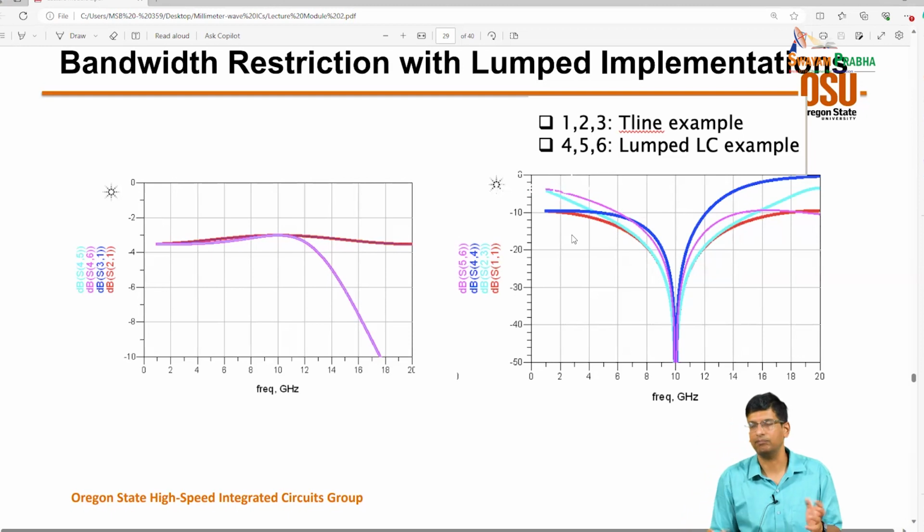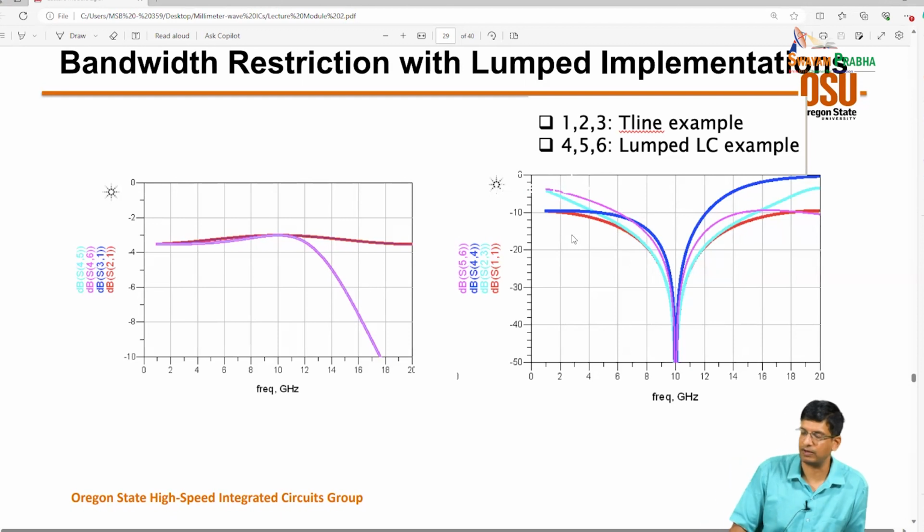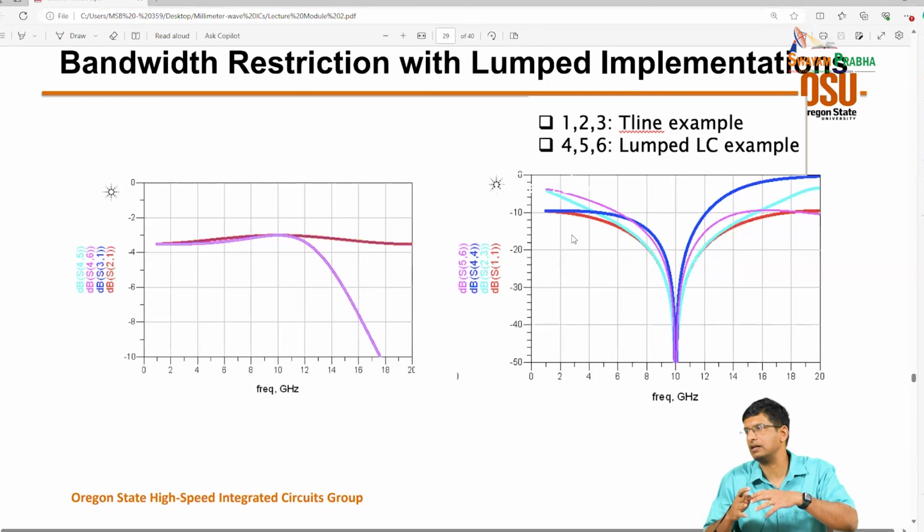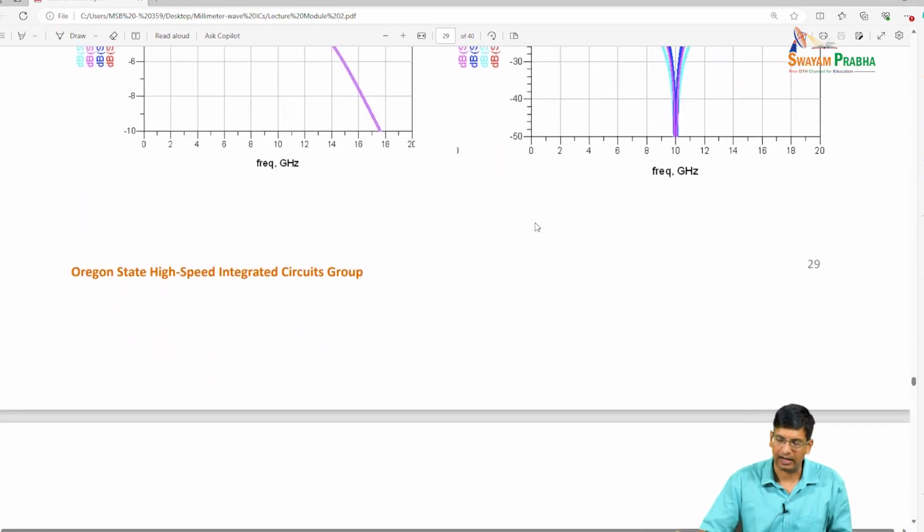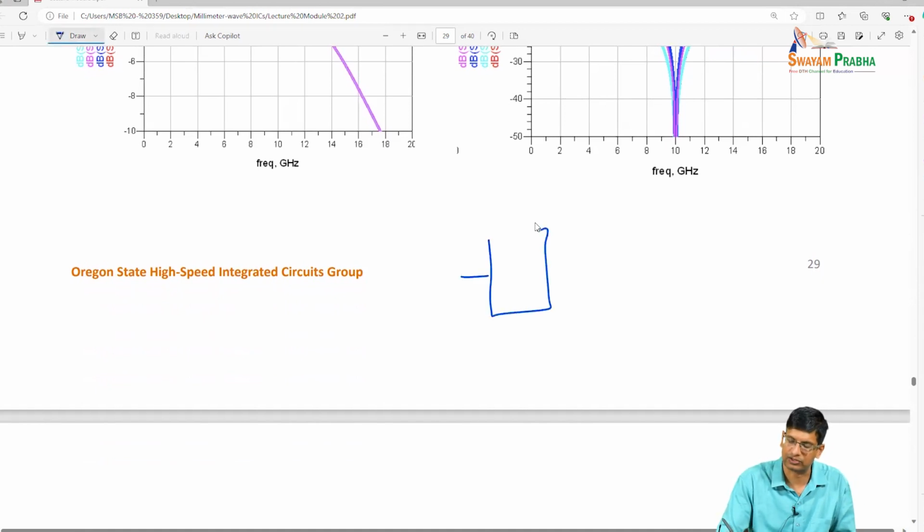And this can be important, particularly in applications where you want to build reconfigurability in your power divider. You want to basically sometimes split power and have both parts operating, or sometimes only one side operating. And again, this kind of approach works. The Wilkinson's isolation is really helpful when you are feeding power, for example, to two blocks.